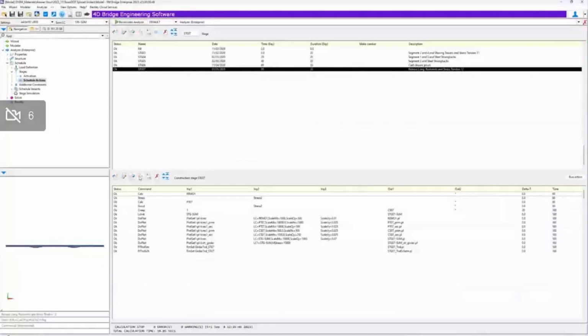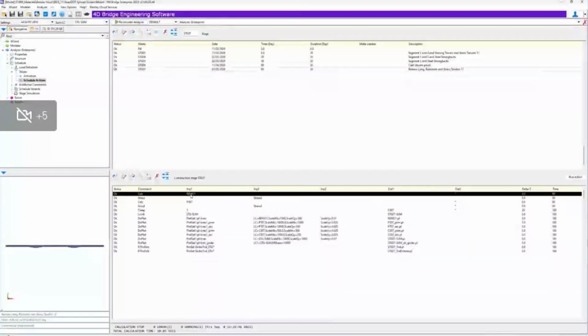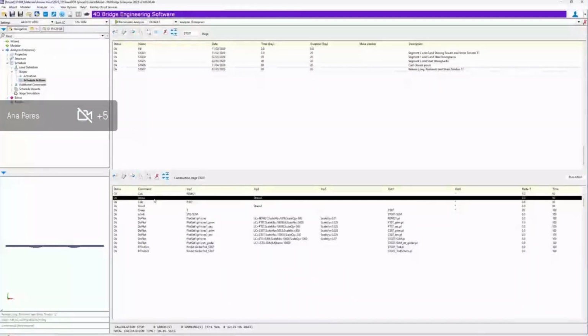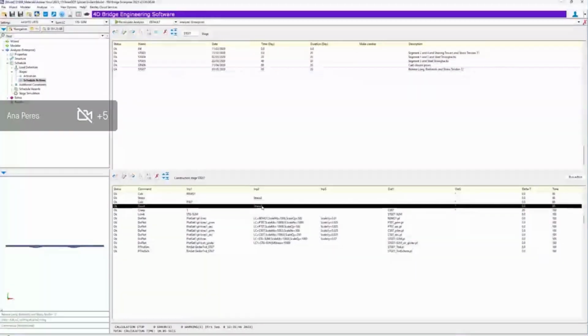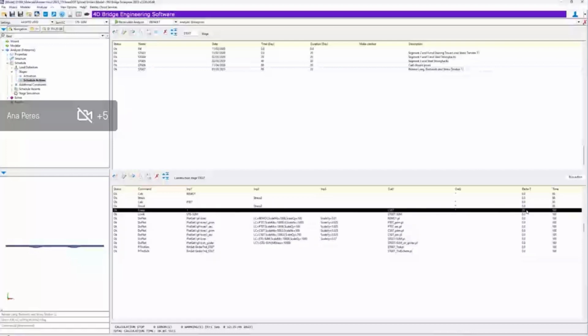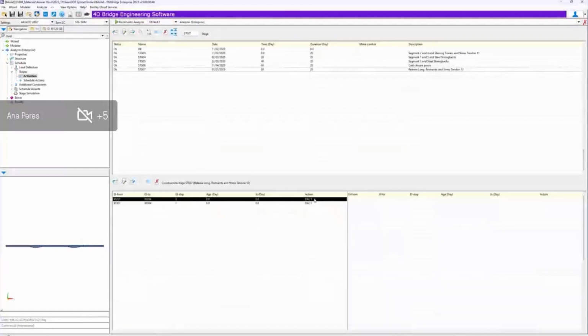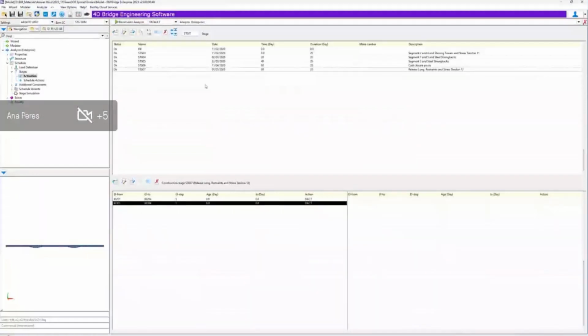So at stage 07, the load case RAM01 is calculated, installing the first continuous post-tension tendon with the stress, calc, and grout, and considering the creep and shrinkage effects. At the stage activation, we are deactivating the temporary shoring tower supports and the steel strongbacks for longitudinal movement.